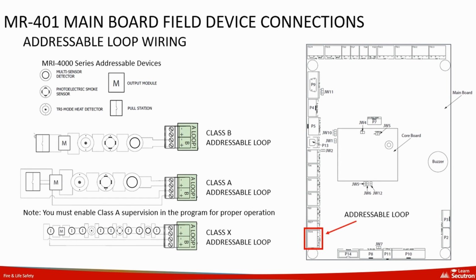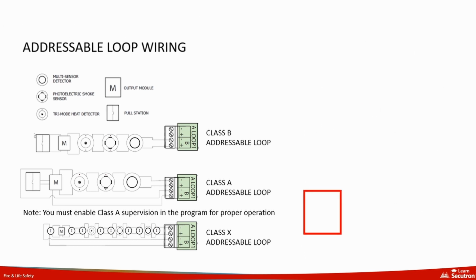To connect addressable field devices to the MR-400's main board using addressable loop wiring, Class B, Class A, and Class X addressable wiring is compatible as shown. Note the importance of enabling Class A supervision in the configuration software when using Class A-style SLC circuits.